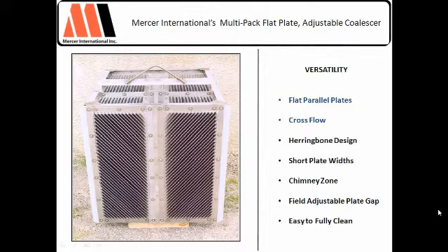So if you move to a cross-flow design, like we have here, water's flowing here, and water flows through the separator all the way to the back end. Water, oil, and solids all are heading in the same general direction. With that, you can keep the plate gaps here much tighter without the same fouling.